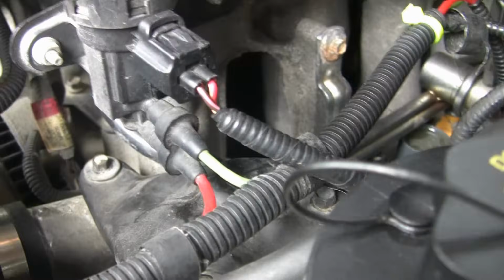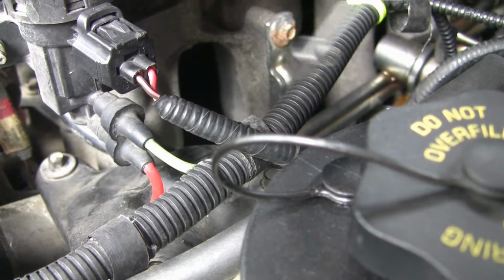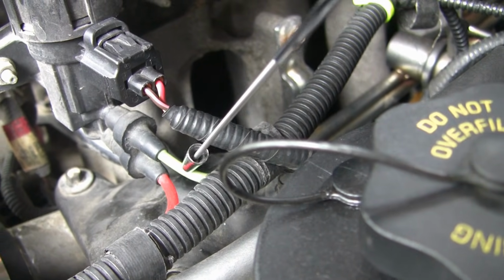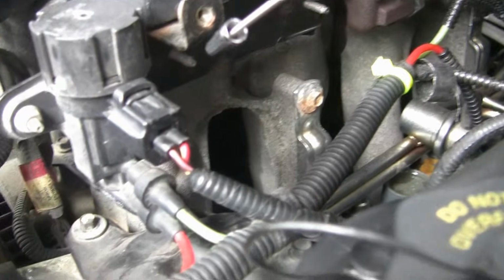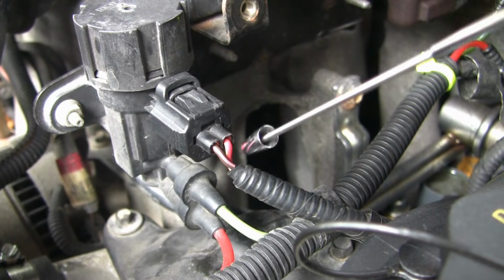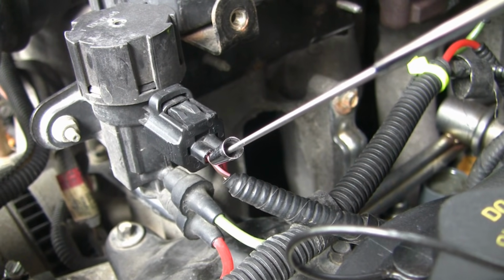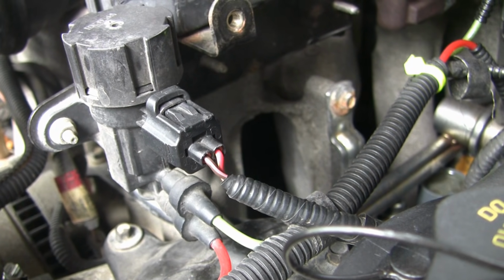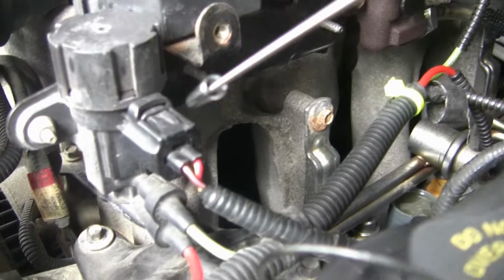And you'll see there's two vacuum tubes coming into this thing on the bottom. The red one is your source vacuum coming from the engine, and then the green one is the one that goes out and connects to the top of the EGR over here. And there's also an electrical connection which has two wires. One is a 12-volt reference, and the other one, depending on the design of your system, will either apply 12 volts or apply ground, and that causes the solenoid to activate and allow the vacuum to pass to the EGR, turning it on. And I'm not sure, but this is all controlled by the computer.